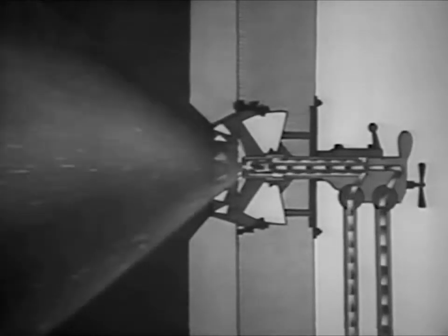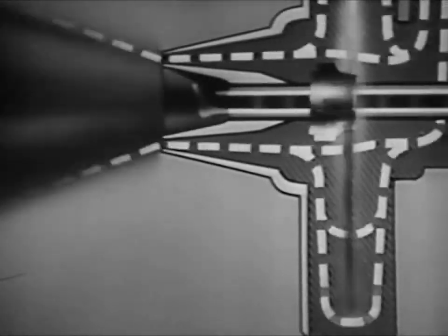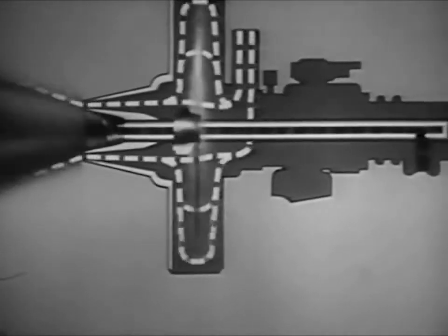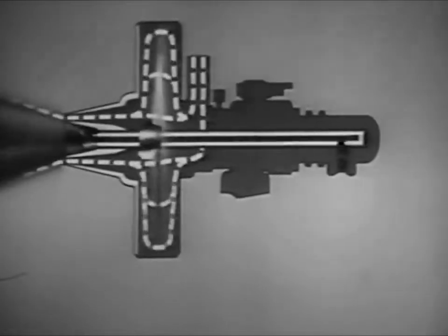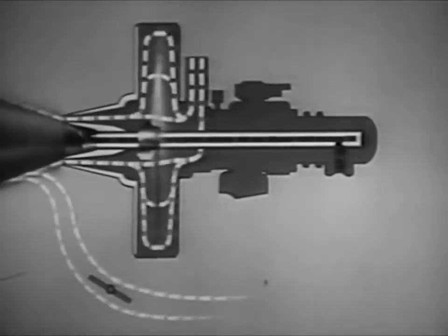In the return flow burner, you vary the pressure on the return oil line to control the amount of oil entering the furnace. In the rotating cup burner, the action of the rotating cup and the air from the blower atomizes the oil. Additional air enters through the damper door.